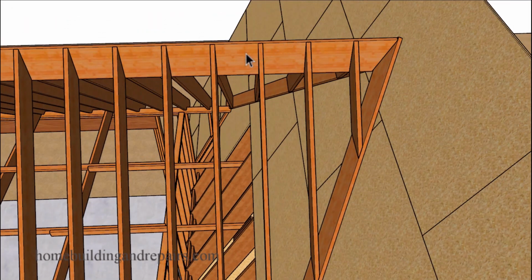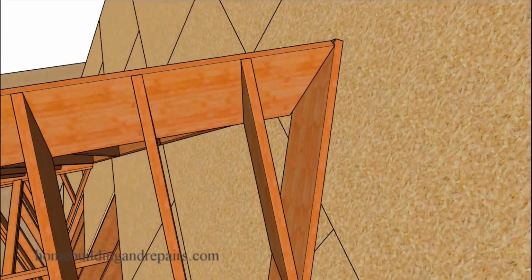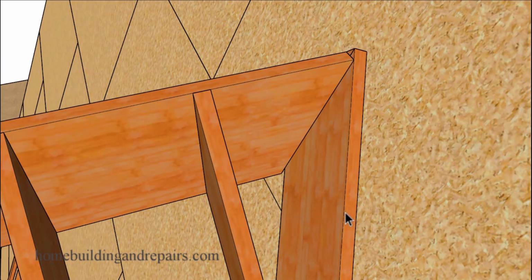And I went ahead and had the ridge sit on top of our support boards here. You can always have the ridge sit on top of the sheathing, but I went ahead and did it so that I could show you how these support boards basically go up and kind of form a peak here, where if I was to run this through and have it sit on top of the sheathing, I just wouldn't have this. And I would imagine some engineers would rather have the ridge sit directly on top of these support boards instead of the roof sheathing, especially if the ridge won't be sitting on top of a rafter.